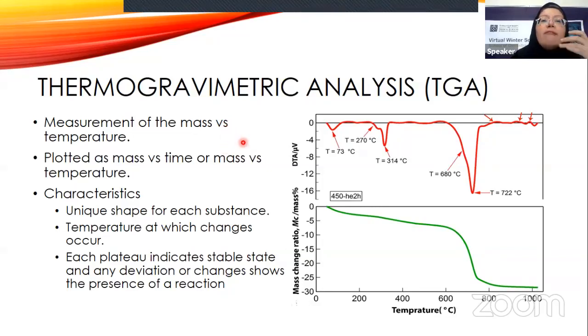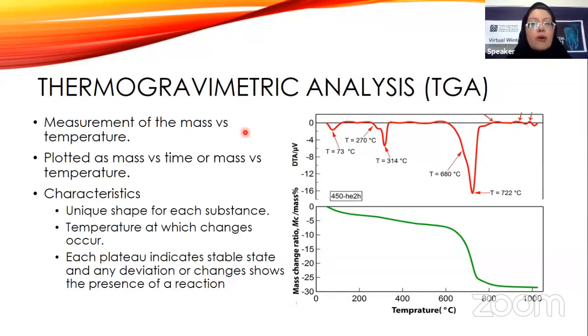And so maybe for some materials, if we want to do any thermal treatment, we have to stop our thermal treatment up to this point, because after this point the material goes to burning or maybe goes to evaporation. Some parts of materials go to evaporation. So we have to consider the changes of weight of material, and we can measure these changes using the thermogravimetric analysis.